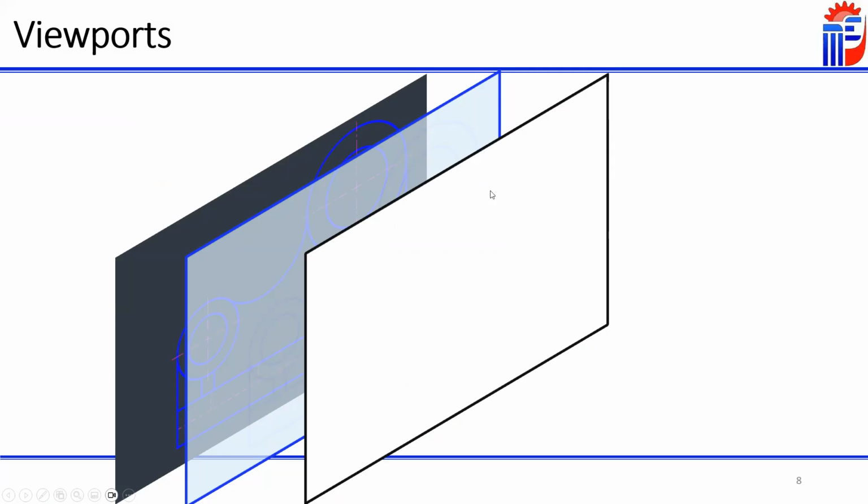Now to see the drawing that is behind the paper, you need to create a cut, right? Otherwise you will not be seeing the drawing which is behind it. The cut that you are going to make is called a viewport. So we are going to cut a paper here.